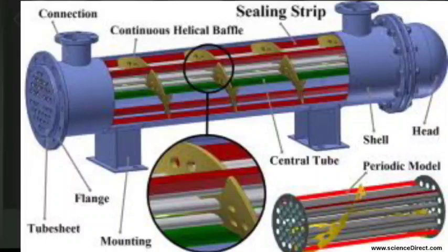Now we have created this as per some technical advisor also. And the second one is we have to provide sealing with overlapping area of both baffles, and it must be maximum 75 mm to the edge. Okay, gap should be maximum 75 mm from the edge. Yeah, maximum 75 mm from the edge, for vertical and for horizontal, the baffle cut edge.